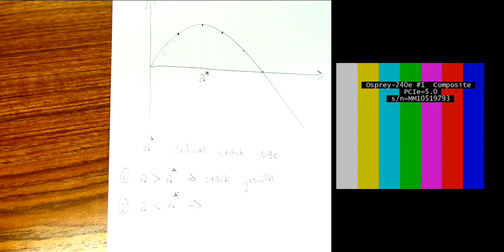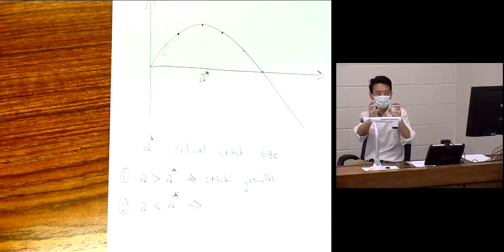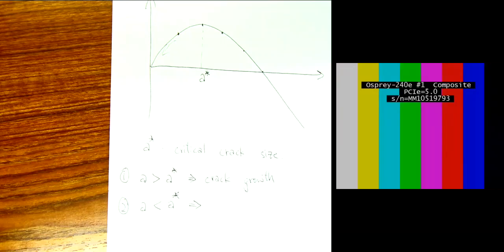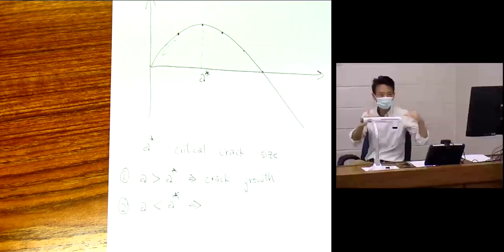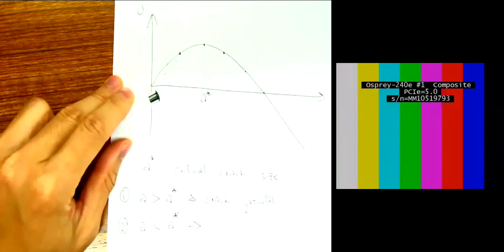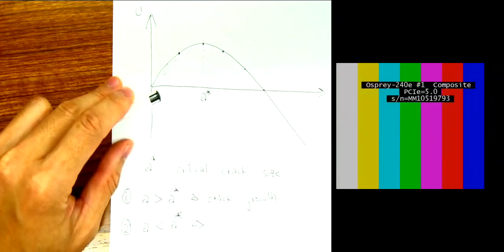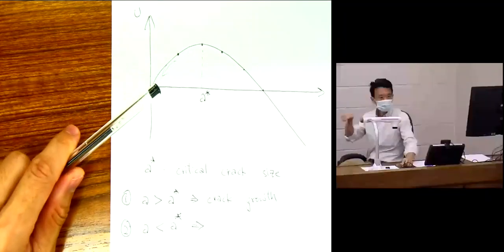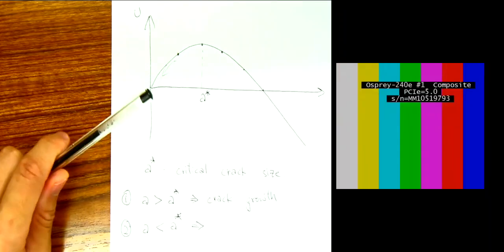The small particles start adhering to each other. So if you think about that process, it's like crack healing, because at the beginning you have these particles that are not combined, but after the process they are combined. But you need to reach certain conditions. For example, the first is that it needs to have enough mobility for the two particles at the atomic scale to do this process. So the analysis is not wrong, but for the physical process to happen, there are more conditions. Thermodynamics predicts that if the conditions are right, you're going to get that process.